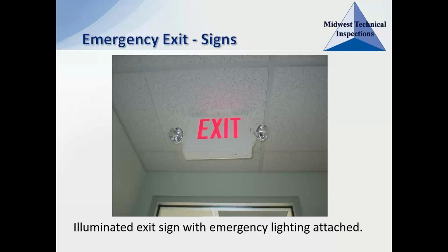So generally speaking, if you have a place where you have a lot of people that aren't normally there, that aren't necessarily familiar with the building, that definitely needs to have the exit sign. So any kind of occupancy that would have visitors, like places of assembly, so like restaurants, bars, things like that, where there's people coming in that aren't necessarily familiar with the location, you definitely want to have those exits marked so that if there's an emergency, they can easily spot where to go and how to get out of the risk.